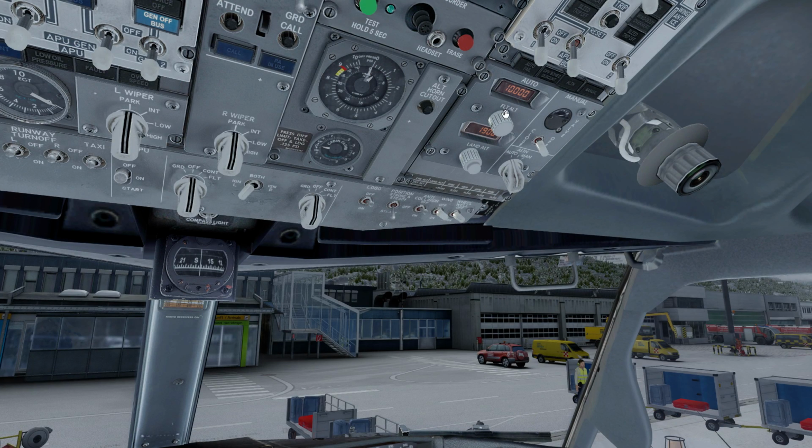Alright, now here we have the cruise altitude and landing altitude systems, and this is used by the aircraft to regulate the pressure of the cabin properly. So what we want to make sure is right now for Innsbruck, landing altitude has already been set. When we land at Amsterdam we can put it at 0 feet pretty much, and right here we're going to put our cruise altitude. Initial cruise altitude today is flight level 380, and we want to make sure that this switch is set to auto, so that the outflow and the cabin pressure regulation is taken care of automatically.